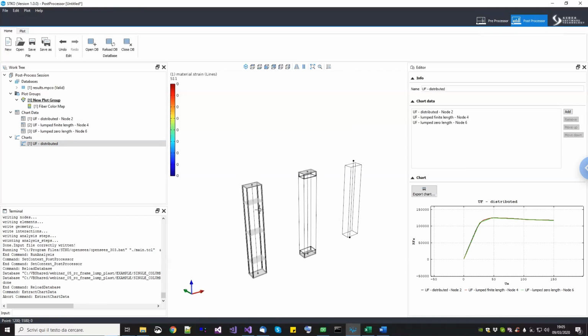There is a difference if you want to use an elastic element with different cross-section. Then the elastic force beam column will give you the exact response, while this one will only impose a compatibility condition instead of an equilibrium condition. But in our case, it is the same. Then there is a difference in the way they accept the material model. So the elastic beam column accepts an elastic cross-section, while the elastic force beam column needs also the integration scheme. So that's why there was that error before.